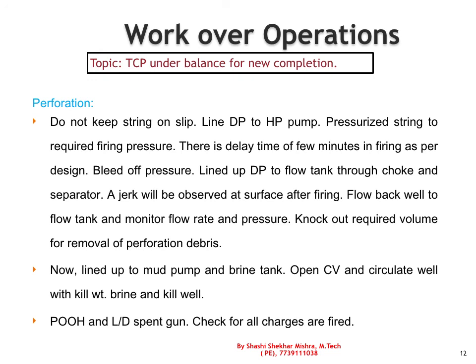So once it passes the 6 to 7 minutes, a jerk will be observed at the surface after firing. Sometimes if the charge is very small, the jerk cannot be noticed. So then we line up and make the well flow 1 to 2 drill pipe volumes just to knock out the debris of the perforation and the charge. And after the knockout is completed,